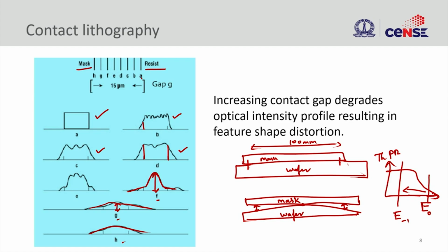Okay. So it is very important to understand what is that level beyond which you will not have any illumination at all. Because the reason for this is in proximity printing, we give some gap, right, and there we know the gap, so that we can actually calibrate our dose, or the intensity of light that we are going to use in this exposure. But in hard contact, always you presume there is a good contact and your dose is going to be dictated by that contact, right.